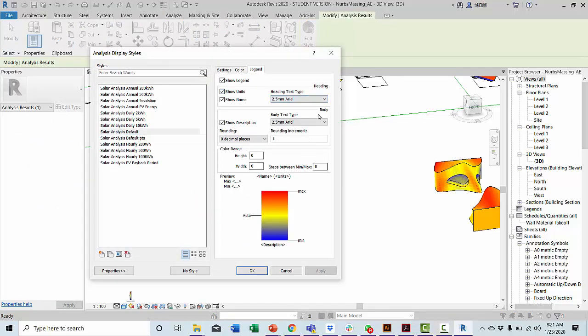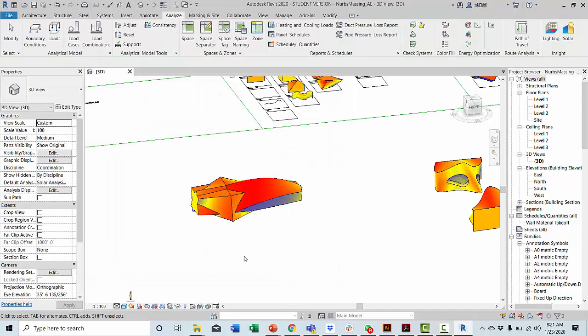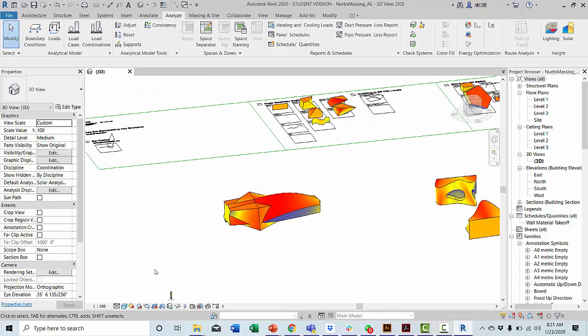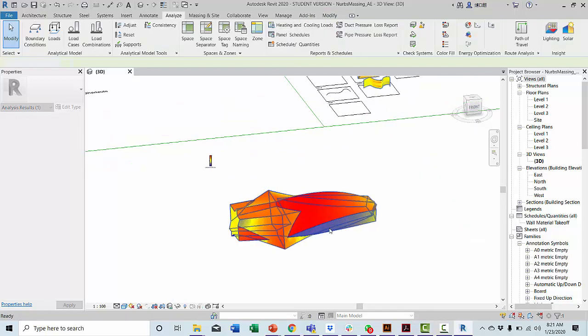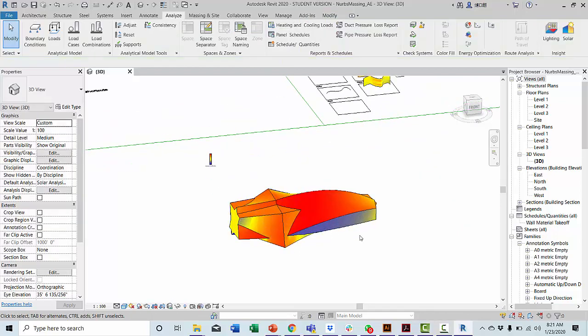Whereas if you're in a hot and humid climate, you probably don't want to have windows there. So you're going to be looking at things like your site conditions, like where you want to have views, where's the access to your site in order to make the form, but then also taking into account the solar radiation that we're looking at here. And of course, prevailing winds, which we're not doing for the first assignment, but we'll follow in the second assignment. But you guys should already be thinking about prevailing winds from conceptual design already.